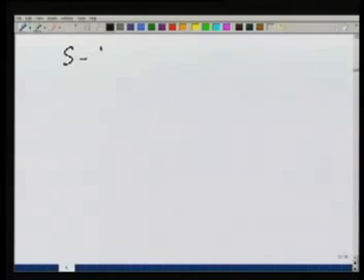Now we should look at how to derive the IUH. As we have already discussed, it is a very small duration rain, total depth of 1 centimeter. So one way of deriving the IUH is using the S curve. Now we have seen in the previous lecture, this S curve is the direct runoff hydrograph because of an infinite duration of rainfall.